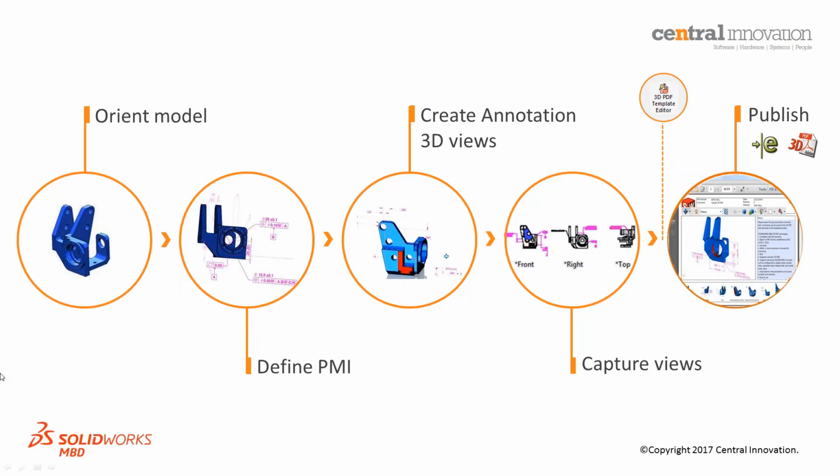To start with the third step, you start just creating the views and assigning the annotations to them. So that's kind of a very easy thing. It's almost like just click of buttons and you get all the views that you need. You can set up multiple viewports with your product manufacturing information, have cut sections, bill of materials, model break views, and all of that. I'll show you about that as well. You can capture views with a click and choosing annotations for the views to be captured. You can adjust display states.